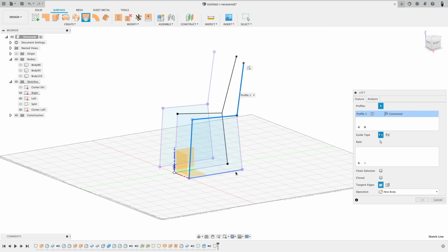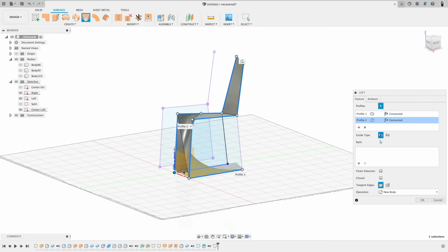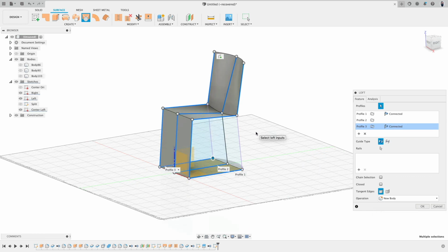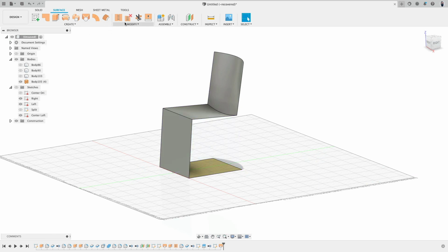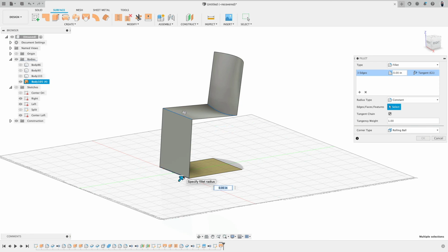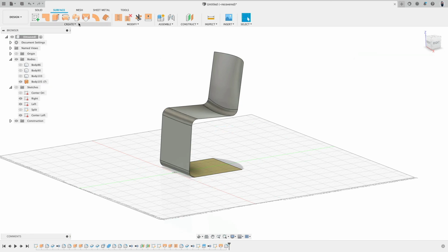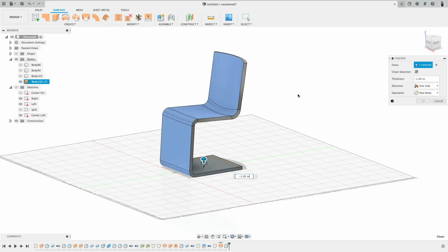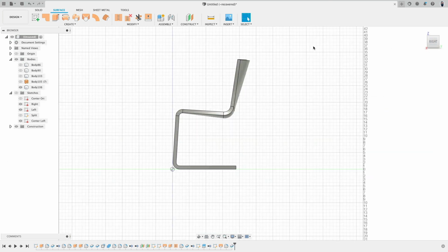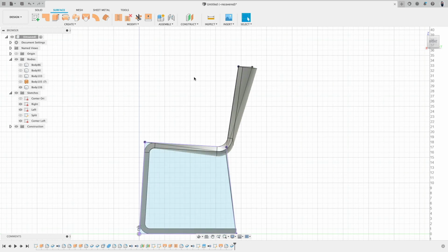Okay, now actually it makes sense to loft everything because there's a sufficient amount of difference between all these sketches. There we are. Beautiful. Fillet there, 2 inches. You see, it's very repetitive. Not necessarily said in a negative way, but it makes it very easy to learn.